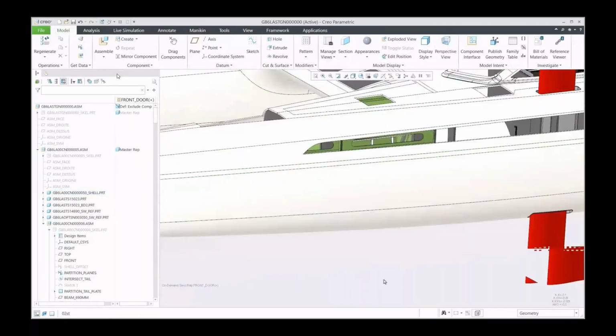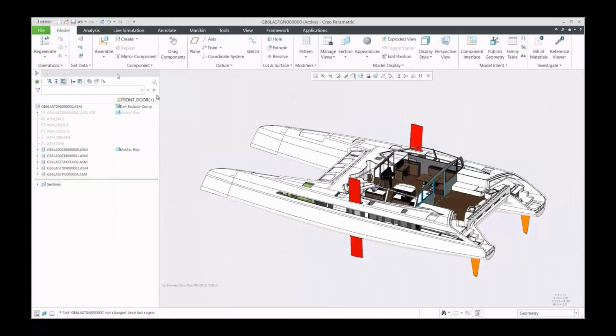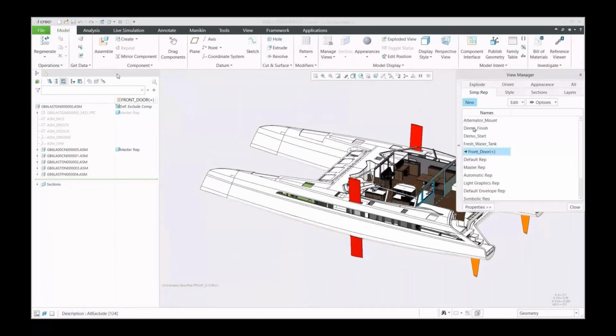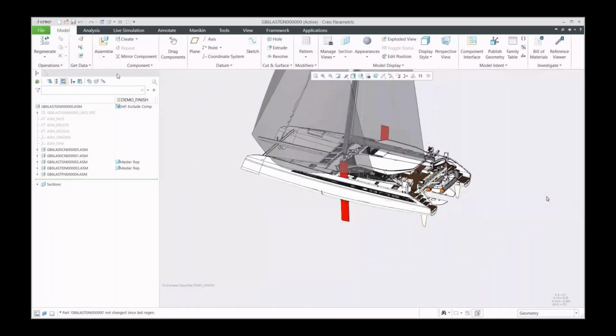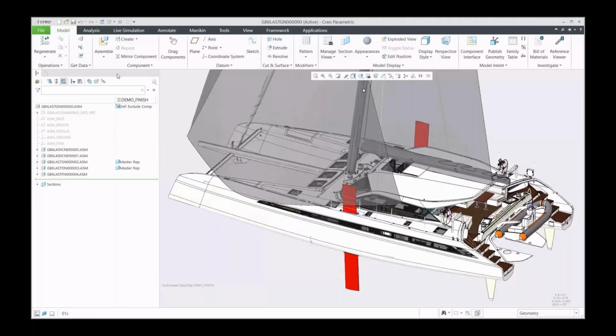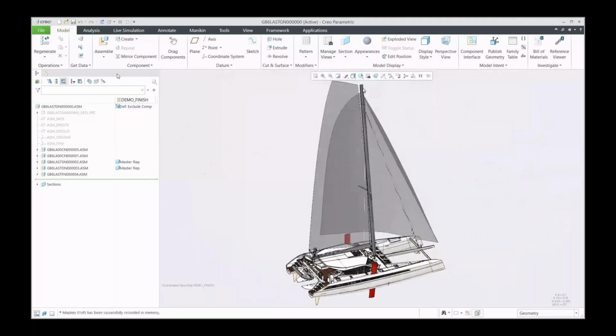So hopefully from some of those techniques, you can start to see the power of how advanced assembly can really start to affect your workflow. It enables your different teams to all be working on their own areas of a design in isolation, but within the context of an overall assembly, leveraging those skeleton models to share the critical design information down to those design teams and hang their geometry off of, therefore making it easier to make these design changes through the use of skeletons, shared copy geometry, shrink wraps for working in context of other teams and designers and those sorts of things.